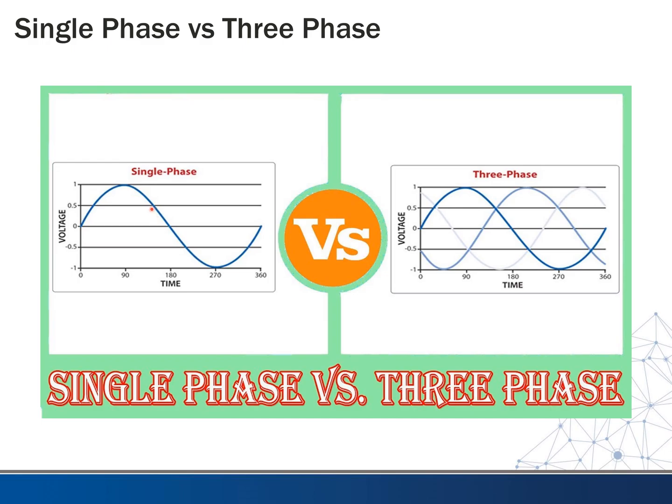All right, and then you can see between the 0 and the half mark here, half peak, and down here as well, not a whole lot of power is being delivered to the motor. It doesn't have consistent drive on it. So if you have a pretty heavy load on that motor, this can cause an issue, and it makes it difficult for the motor to maintain torque. And so this can be a really big problem in industry, when they have assembly lines going and they have different processes going, especially with loads that are under heavy load.